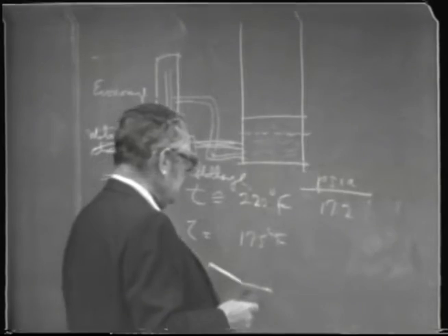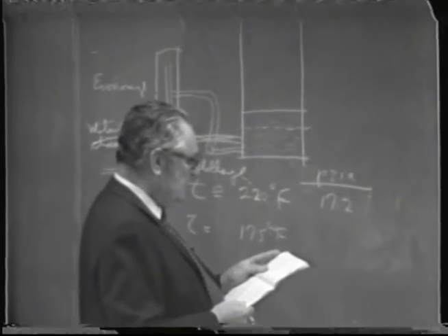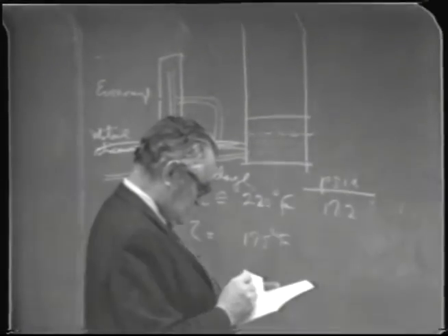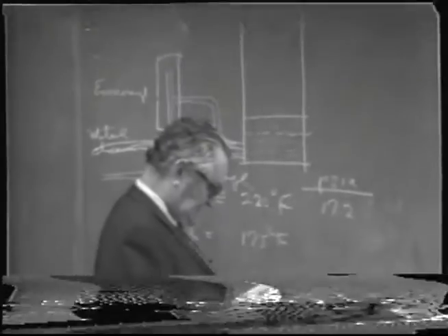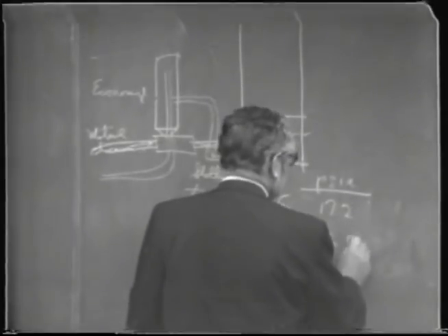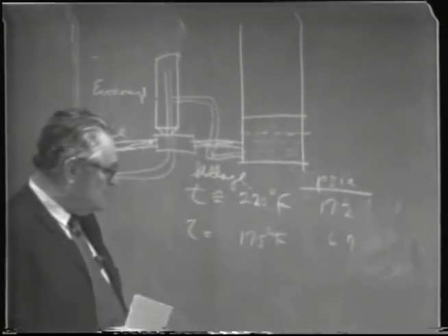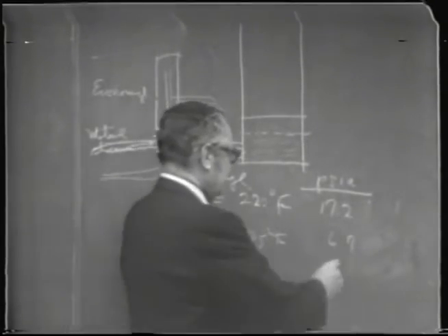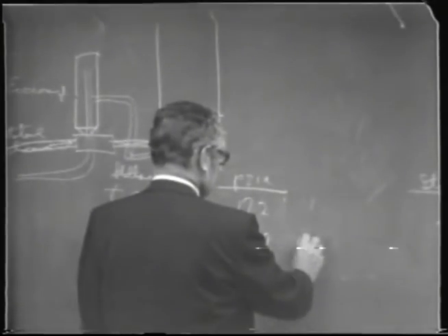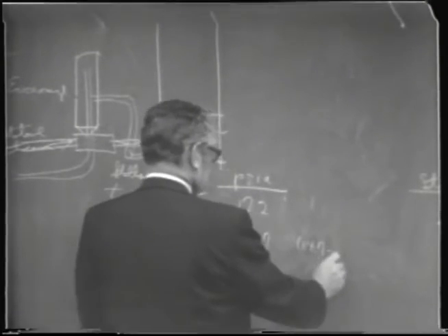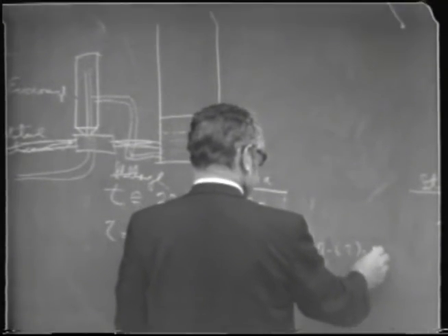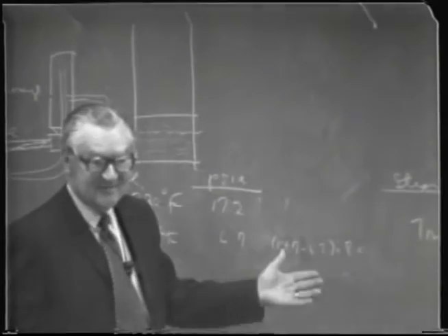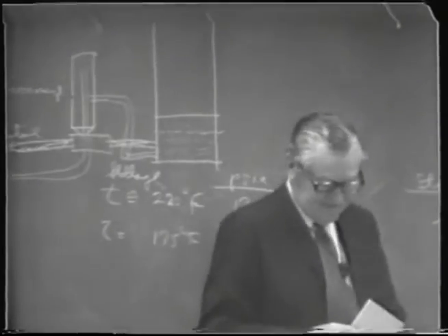If you can drop the temperature down to 175, by lowering the pressure to roughly 6.6 or 6.7 pounds per square inch absolute, or a vacuum of around 14.7 minus 6.7, which would be 8 pounds per square inch of vacuum, or negative pressure, you could say it that way.